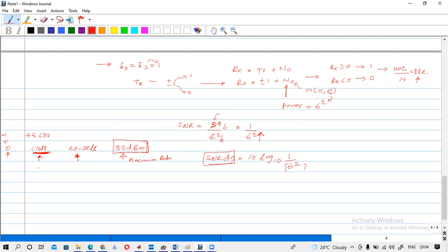So you can see that based on the SNR dB value, our bit error rate will change. How does it change? When we change the SNR dB value, we change the sigma, we change the noise power. If we change the power, the received signal can also be subjected to change, so that it will create errors.